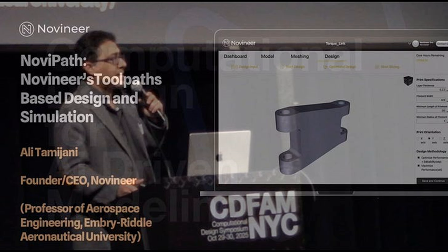This is what conventional slicers can do. And these are the two that we have done, optimizing the toolpath. That's huge, right? And you can also look at the failure analysis, look at the failure index, where the weakest part is, how you can make it stronger, and all of that. Okay, great. You optimize the toolpath, and sometimes you don't want to go further, because if you change the geometry, then there is going to be design review, design committees, all of that, right? But if you have the luxury to change the geometry and toolpath together, that's where this one will help, right?